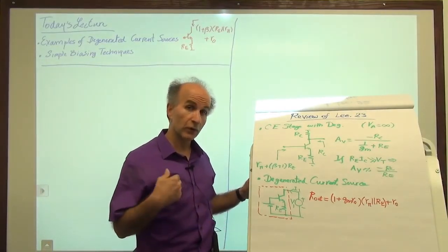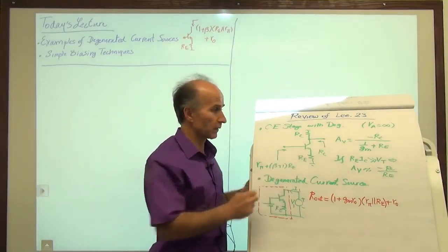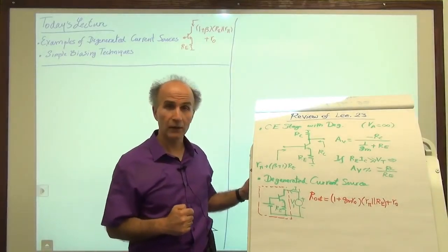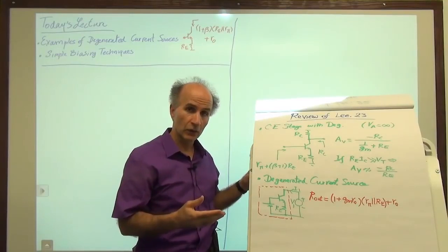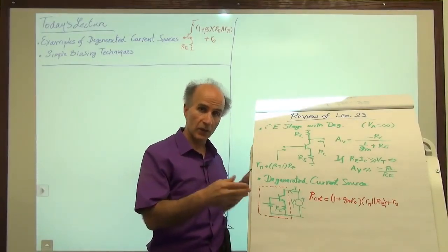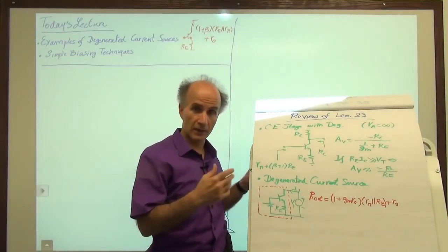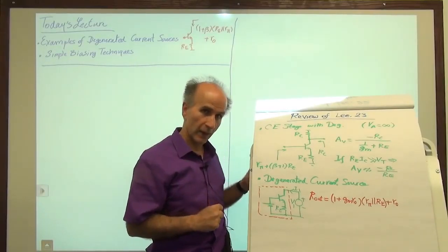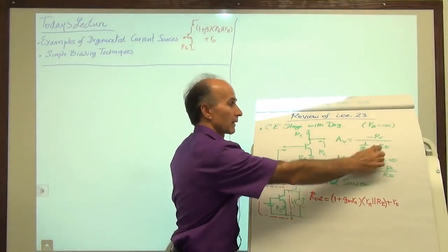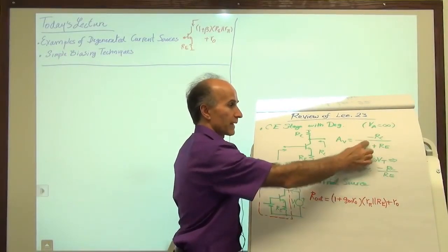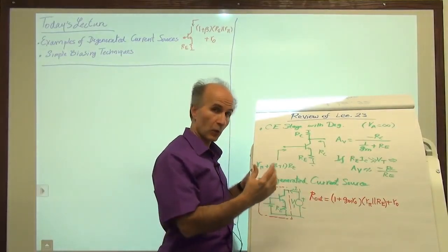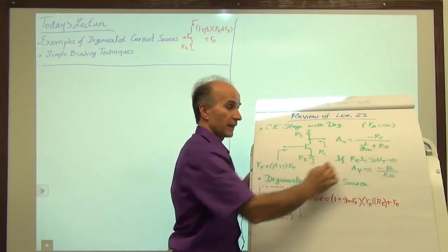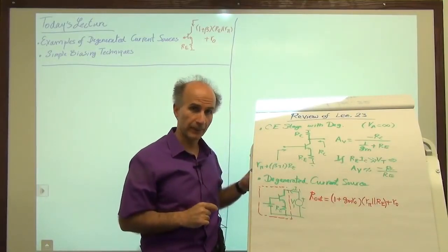And the motivation for using this resistor was that the overall gain of the circuit becomes less sensitive to process variations, to current variations and temperature variations and so on, as we can see by this equation where, for example, variations in the collector current are swamped by this constant value Re.